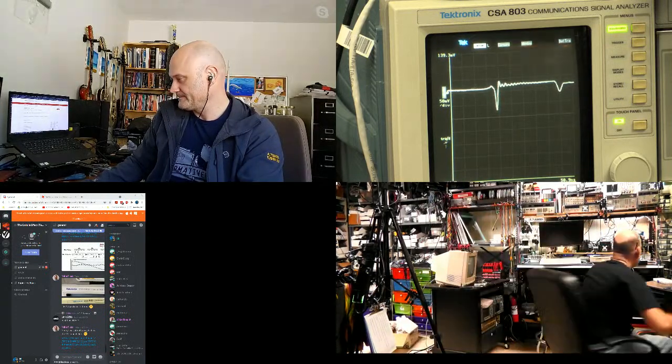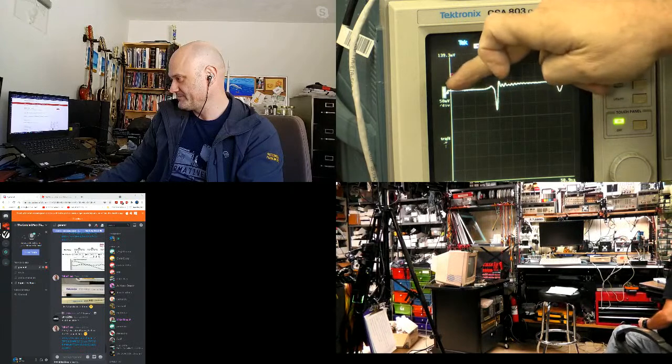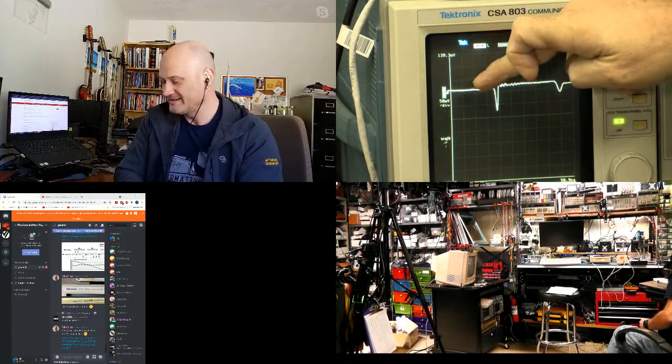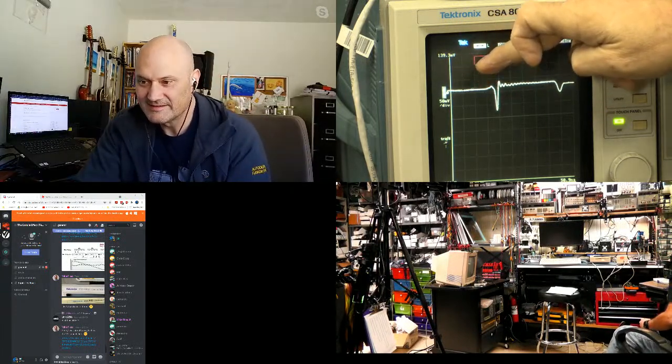That's cool. And I see an inverted spike there, which I assume is a connector or something. Right. So what I've done is I've taken a good quality cable. It goes to the board, and then at the other end of the trace is a terminator. And what we see on the scope here is the impedance of the cable, right here.